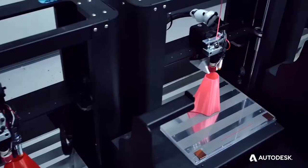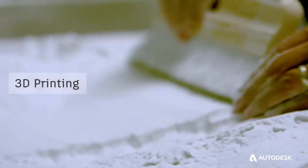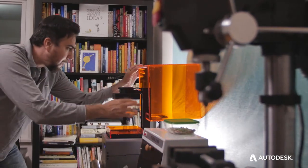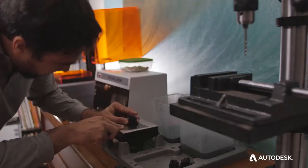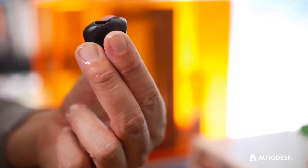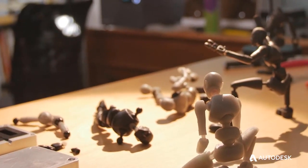Another common manufacturing process is additive manufacturing, which is controlled material addition and is commonly referred to as 3D printing. Like subtractive manufacturing, additive manufacturing can also take many forms, but typically involves adding material layer by layer until the final part is achieved. Since material is being added rather than removed from a solid block, there are features and shapes additive manufacturing can achieve that are nearly impossible in subtractive manufacturing. Internal latticing, sharp internal corners, and tall vertical walls are all much more accessible when produced with additive manufacturing.